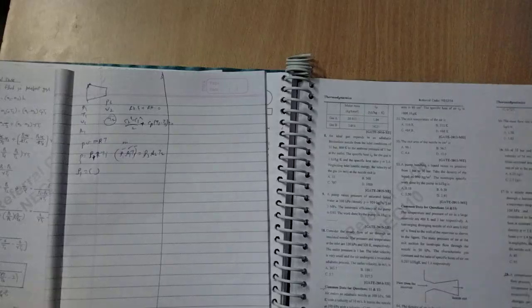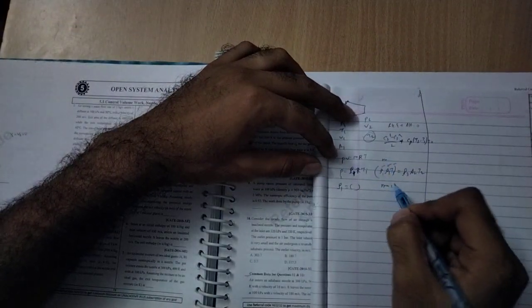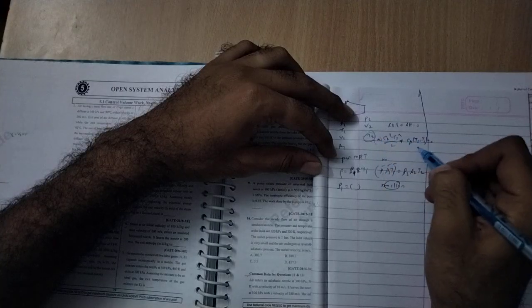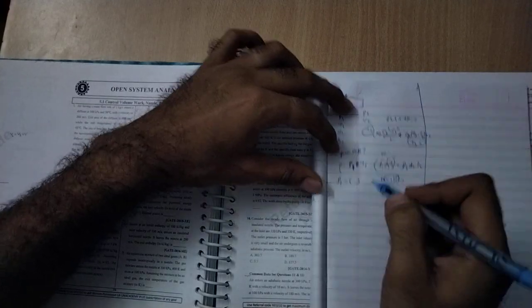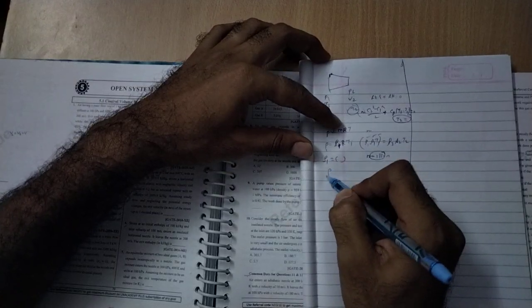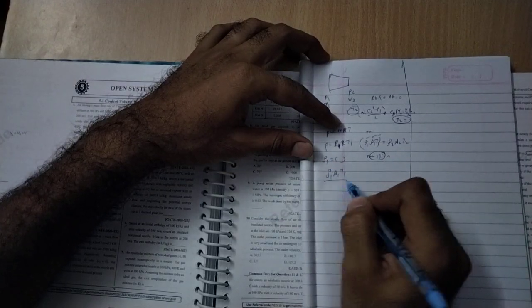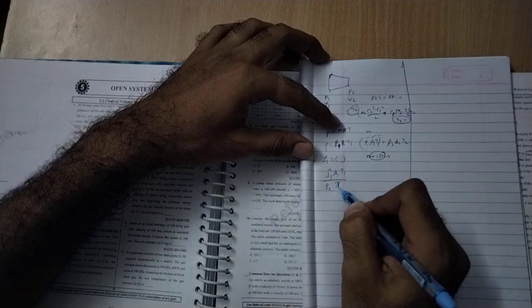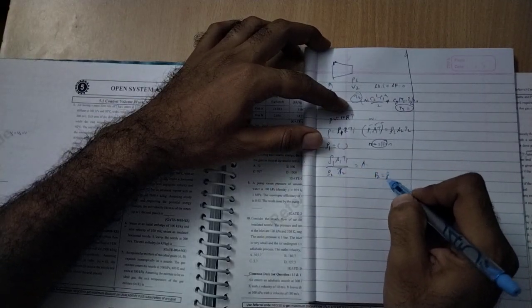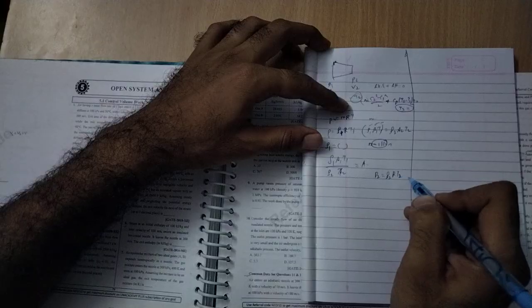Okay, this is also one of the good questions, because as I thought before, they have just taken m1 as 1 kg. By taking 1 kg for m1, you can calculate the T2 here. So next one, this one. By this you can calculate the density, rho 1 A1 of T1 divided by rho 2 of A2 of T2. Density 2 you can do P2 equal to rho 2 R of T2.